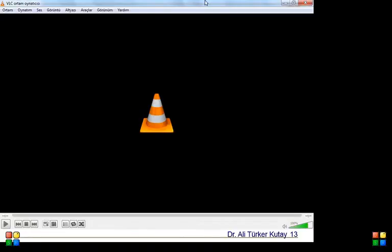Okay, so if you really think about the total energy that needs to be dissipated, consider the aircraft going at about 300 kilometers per hour, and imagine its mass. It's like, I don't know, 200 or 300,000 kilograms, and compute the kinetic energy it has at that point. Now, all that kinetic energy needs to go somewhere, right? And in this case, most of that energy turns into heat on the brakes.